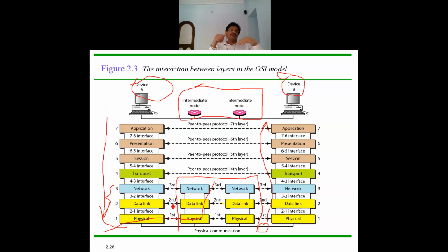So if we are utilizing a differential voltage strategy, then 0 will be transmitted as say minus 5 volt and 1 will be transmitted as plus 5 volt, if we are utilizing positive logic for the communication of the digital data. But this decision of converting this electrical signal again to an optical signal, if optical fiber is utilized as a communication media, is performed by the physical layer.